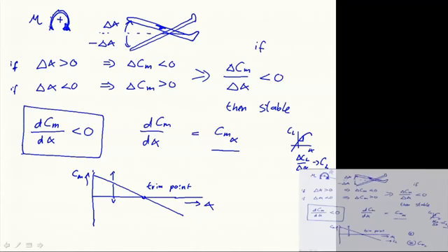Cm when Cl is 0 is larger than 0, and the Cm alpha is smaller than 0. If you have those 2 criteria satisfied, we will have longitudinal static stability. We will not crash, because that's what we're trying to avoid here.